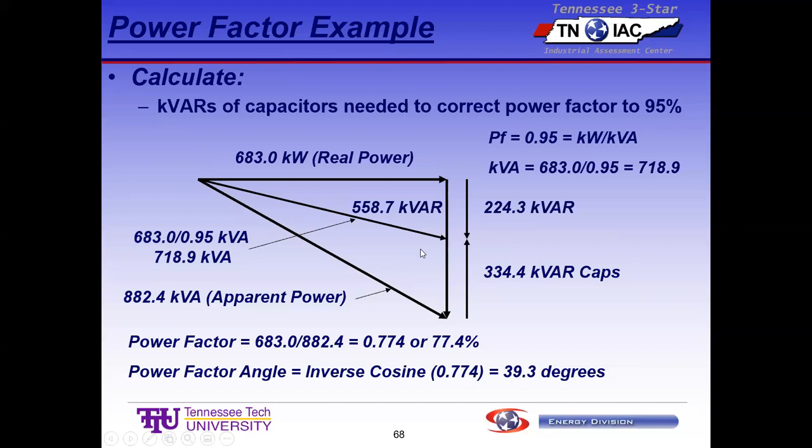Well, we might have MCC number 5 over here, and I have to add another 50 horsepower pump. I've got to have it. And you go in there and say, this thing is pegged. No more capacity. Say it's a 2,000 amp MCC, and you put the meters on it, and it's pulling 1972. And you're going, hey guys, we can't hang another 50 or 100 horse motor on this thing.